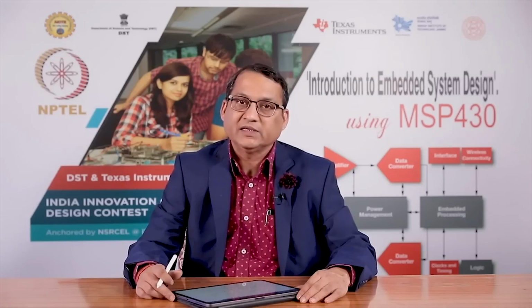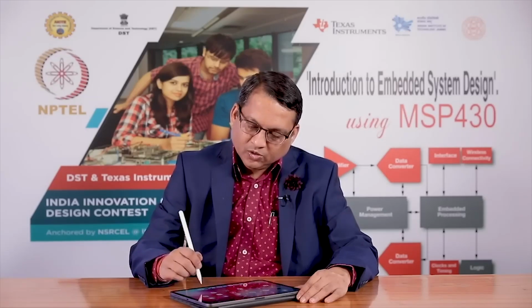But 30-40 milliamperes is a significant amount of current with which to control small LEDs, and so they do not need any other driver circuit to handle them. Also, you can probably turn on small relays with this amount of current, and so having a capability to drive 30-40 milliamperes of source or sink current is a good feature that these modern microcontrollers offer.